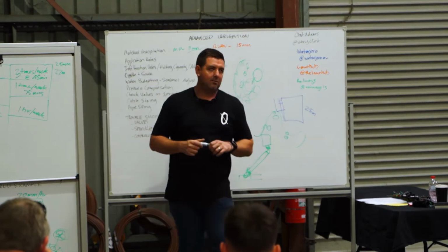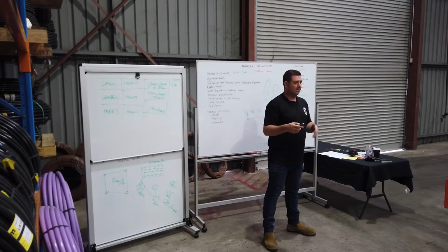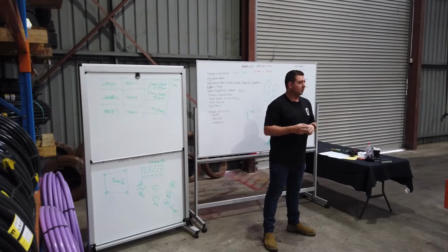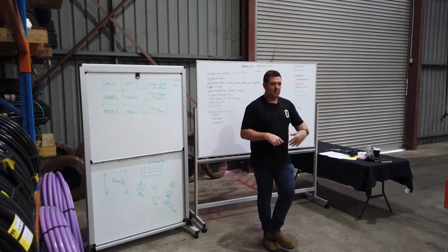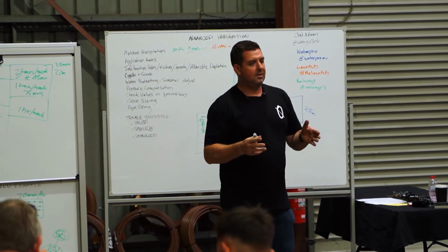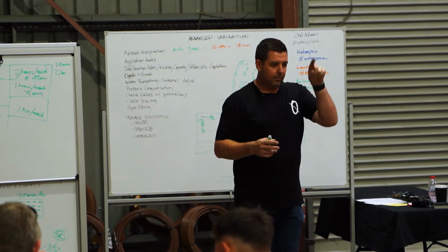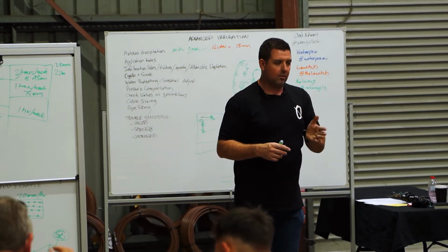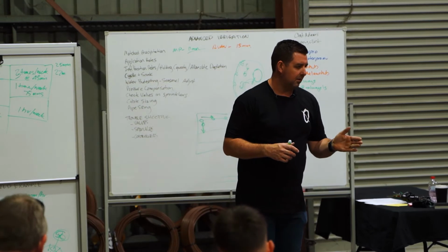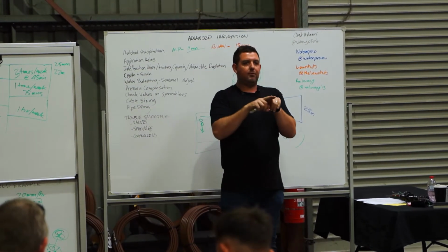YouTube's an unbelievably valuable tool that you've got in your pocket all the time around how to reset a controller, how to reset a valve, but it's probably not as common for you to go, what is the voltage drop of 0.5 cable over this amount of meters? Now, if you have a look at the second paragraph there, there's the 0.5, which is the top line of the top column, and there's about 153 meters. So you can use that chart, you work out how far you need to run your cable.